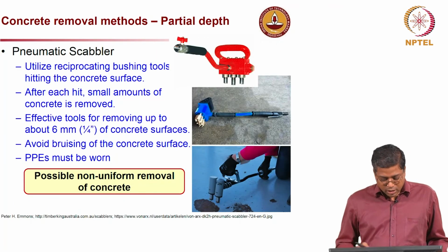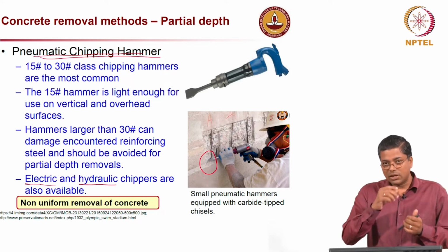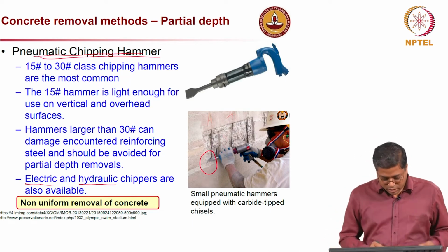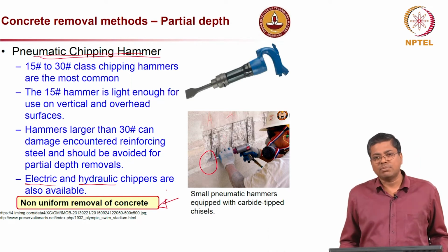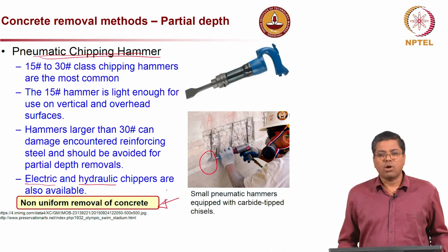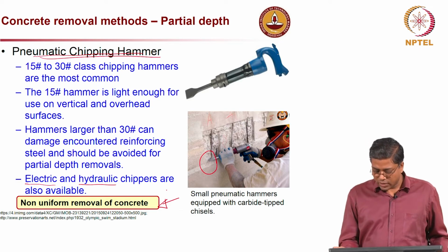Okay. The one thing is there is a possibility of non-uniform removal, depending on the skill level of the worker. At the end you may have a non-uniform surface, but in some cases it may not be a big problem, as long as there is proper cleaning of the surface after removal of the concrete is done.